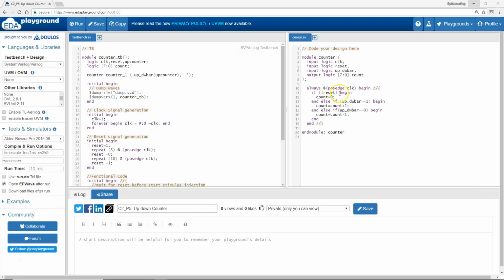If an active reset is present, it should get the highest priority over any other inputs, and should make the output go to the reset state. Here, if the reset is low, output port count is set to 0. If reset is not active, go to the functionality of the circuit.